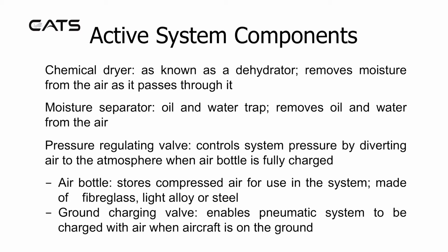The air bottle stores compressed air for use in the system. It's typically made of fiberglass, light alloy, or steel. Ground charging valve enables pneumatic system to be charged with air when the aircraft is on the ground.